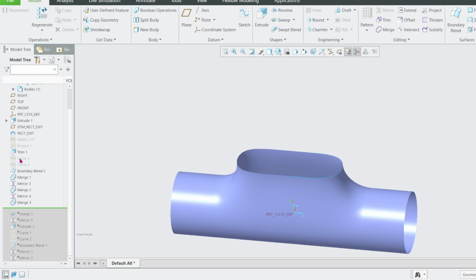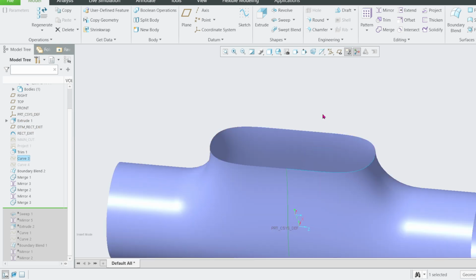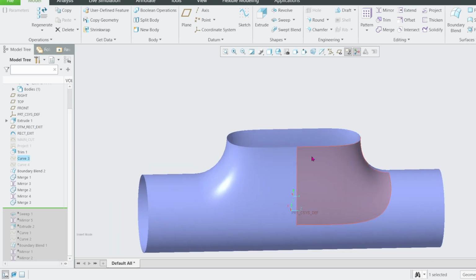This is fixed by these curves. In surfacing, you must understand how to create your curves. You have to create your curves in a proper way. And as I said in my previous video about workflow, for this surface to be tangent to this surface here, at this point they must be 90 degrees, and this must be 90 degrees for them to be tangent. This surface must be normal to a plane that passes here.